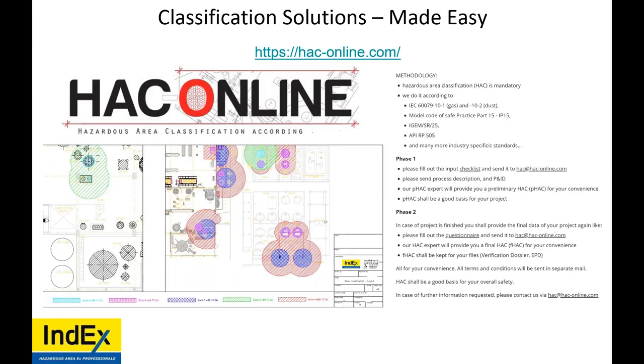It is a contentious issue all the time. So why 2B plus H2 over 2C? If acetylene has not been identified in the hazardous area classification, it's not needed as 2C. You have the cheaper, simpler, more efficient option. The commercial approach is most ideal for everybody,